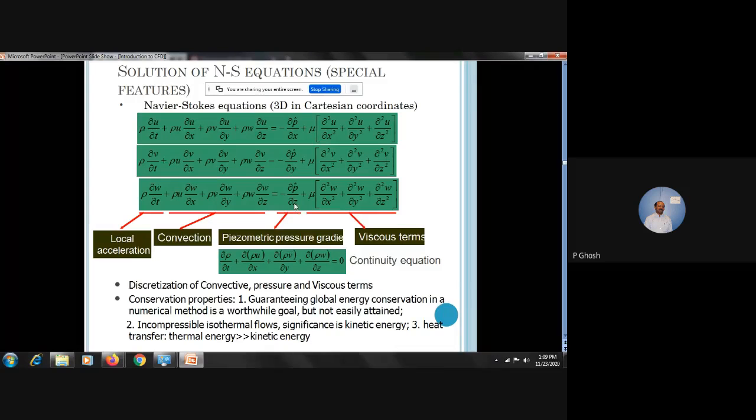And moreover, these pressures are in a gradient form. So the pressure drop in a particular leg, you don't know the exact pressure there, but you have to find out the pressure. So these are the problems. And that's why such complicated equations, a generic solution of the Navier-Stokes equation still doesn't exist for any domain. And that's why we have to do an approximation, and that's why we need a numerical method for that.